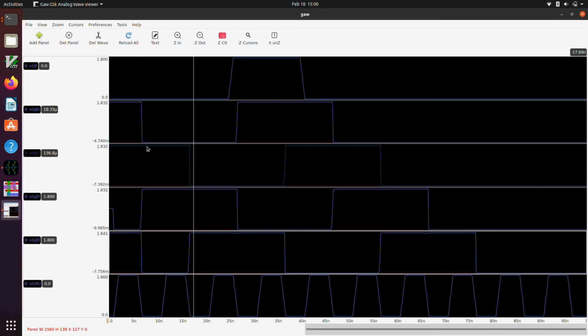So what's up with this? Well, the answer is that we have a bistable kind of circuit, right? So there's two possible ways for the cell to initialize itself. You could have the 0-1 state or the 1-0 state. And just because of the numerics of the way that the transient simulation is worked out, it has chosen to make the output of the first stage initially high.